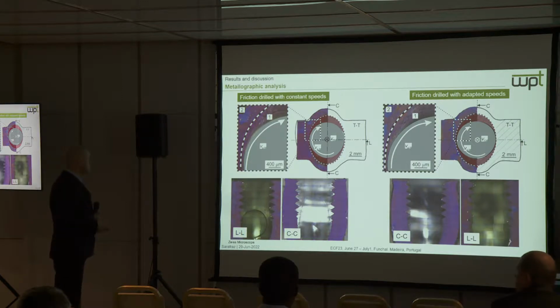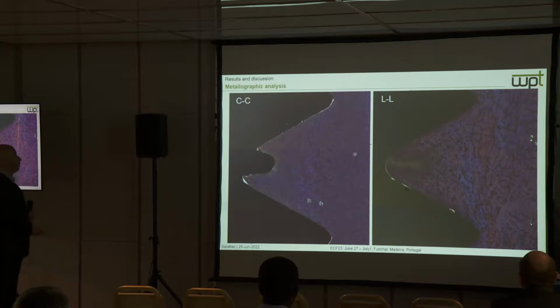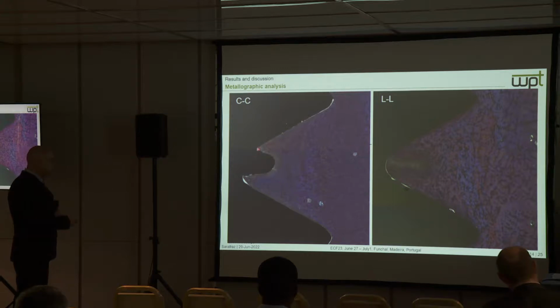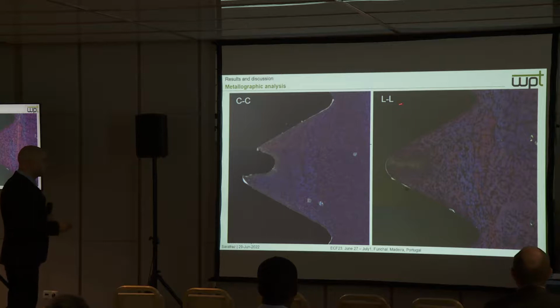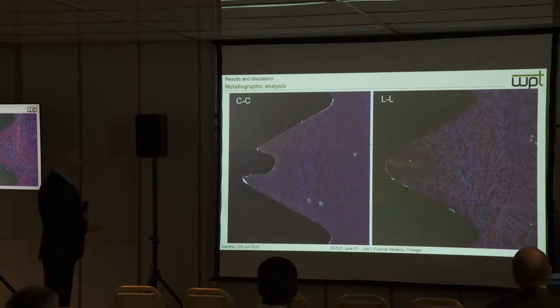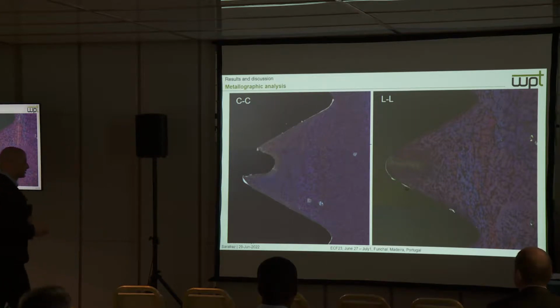The microstructure analysis was continued with the thread. At a bigger magnitude, we can see that the thread was completely located in the cross direction in the friction regions, the sheared and expanded region. However, the thread was not completely formed, and in the longitudinal direction, we can see that the friction region is limited to a small line in the middle of the thread tip.